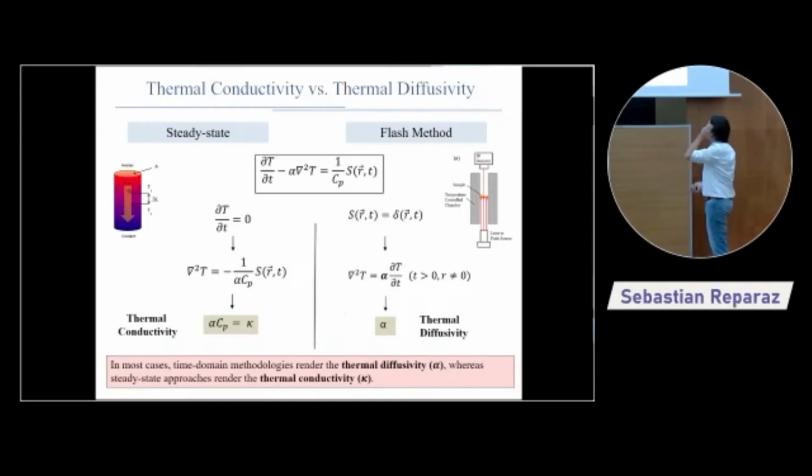You start from this equation that, from all the things that we will discuss during the presentation, is the master equation, even if it's extremely simple. And this is basically the heat equation in the diffusive limit, what is known as the parabolic heat equation. Here, what you see is a dissipative term: the derivative of the temperature with respect to time, the Laplacian of the temperature. This is the diffusivity, and this basically accounts for the heat source, and this is the heat capacity of the material. Okay. So, am I going too fast, or am I going relatively nice? Decent. Okay, thank you.